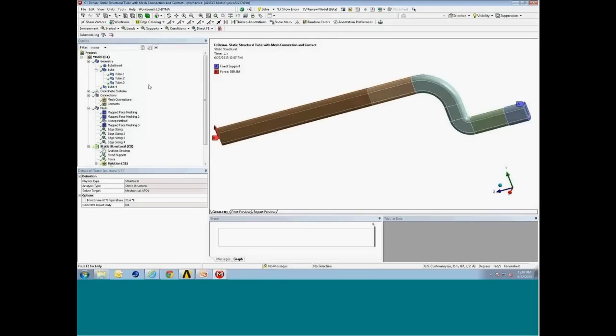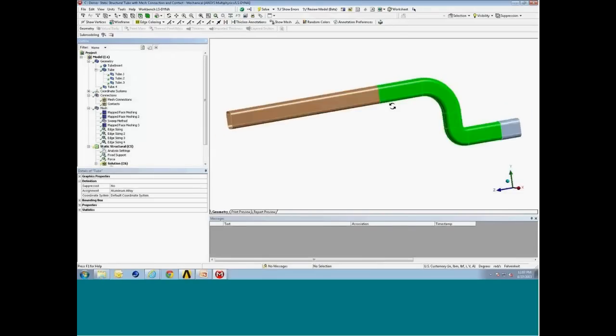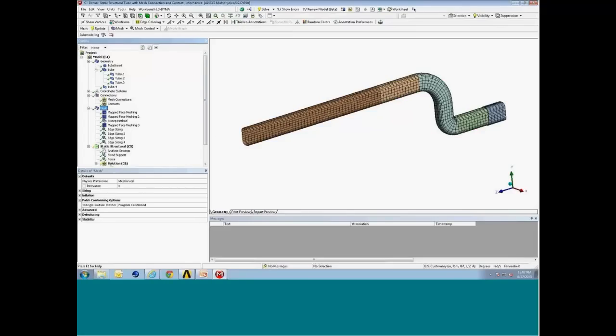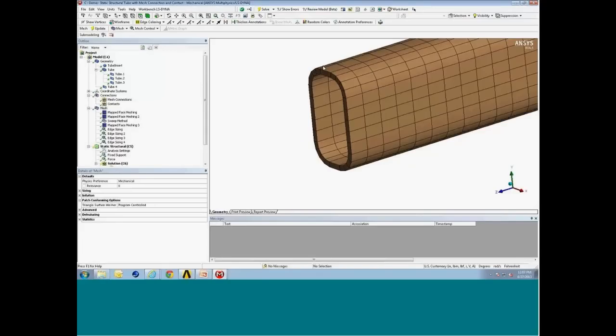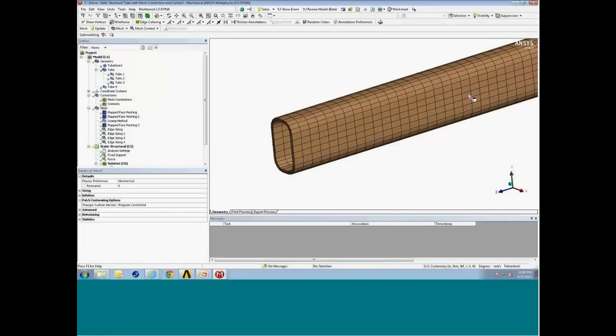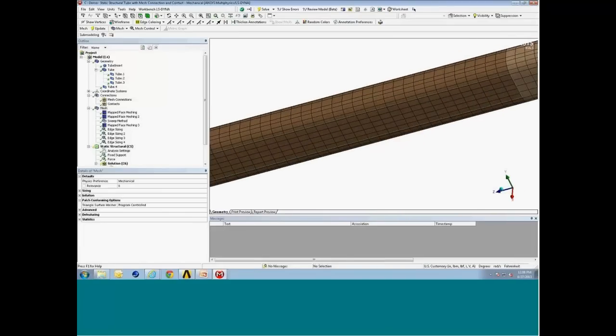First thing I wanted to show you, when the thicknesses come in for the surface bodies, we can look at the visualization. Once the part has been meshed with the thicknesses assigned, we have on the View menu an option to view thick shells and beams. So even though these are surface elements, you can see that the thickness of the shell is actually represented. Sometimes this is helpful for reviewing part-to-part fit and what have you, making sure you can confirm the right thickness of the shell elements.